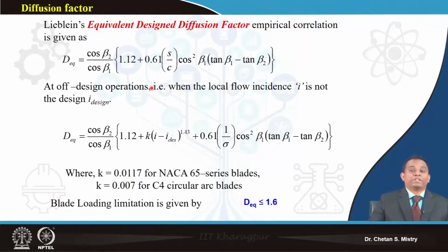That is what is called off design condition. In line with that, our mass flow rate changes from the design condition towards the low mass flow rate side, even towards the high mass flow rate side. Under that condition also, in my velocity triangle, the axial velocity is going to change, and that will change my blade angles or blade incident angles.